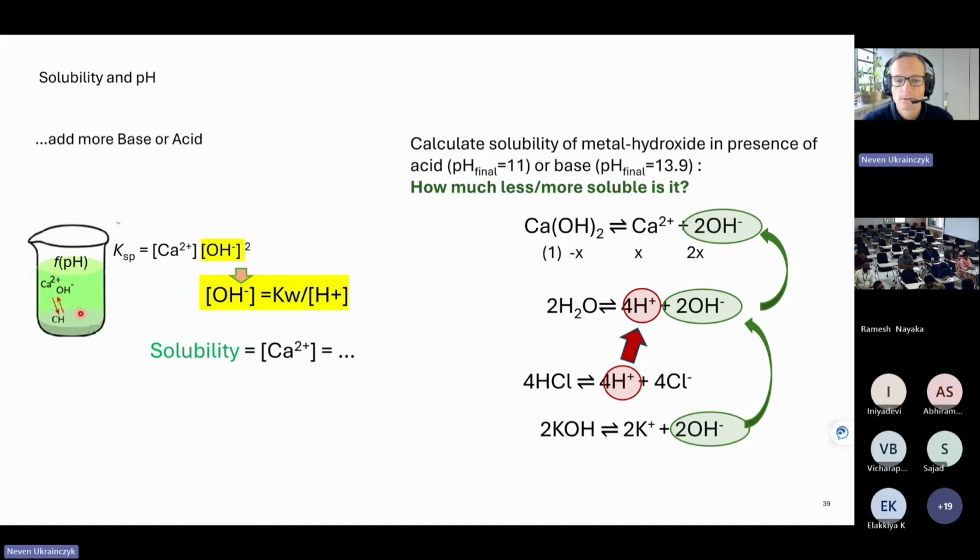So now we have our solubility, we have our portlandite here on bottom, we have our ions here. They are saturated, that means we have saturated solutions, we are in equilibrium, we can calculate exactly how much calcium and OH minus we have. And we also know how much portlandite we dissolved for this system to have so many ions. And this we calculated as a solubility. This was the previous example.